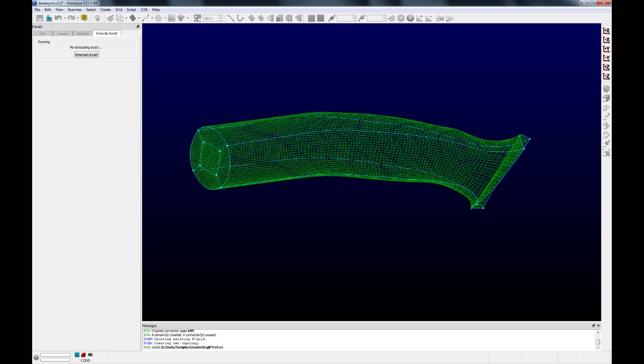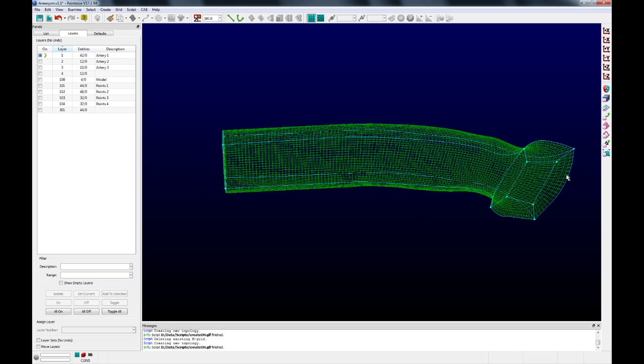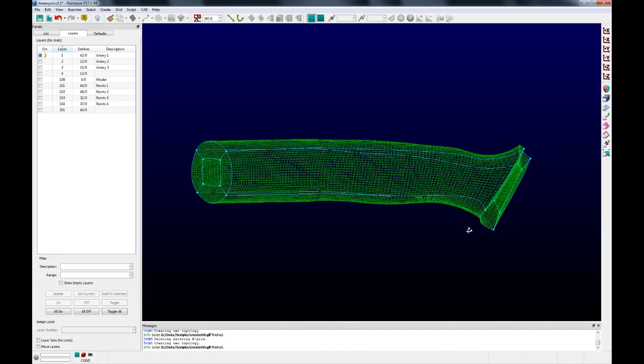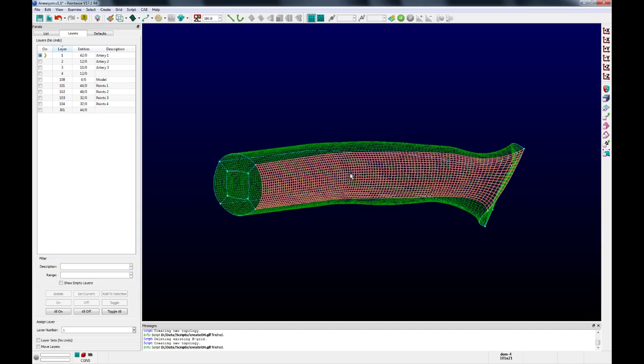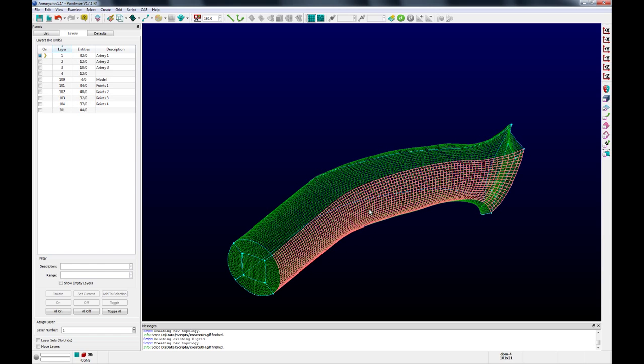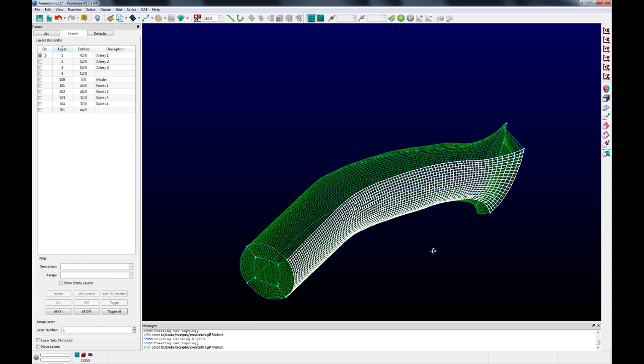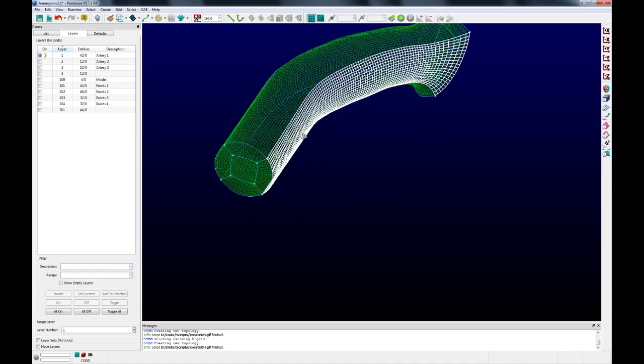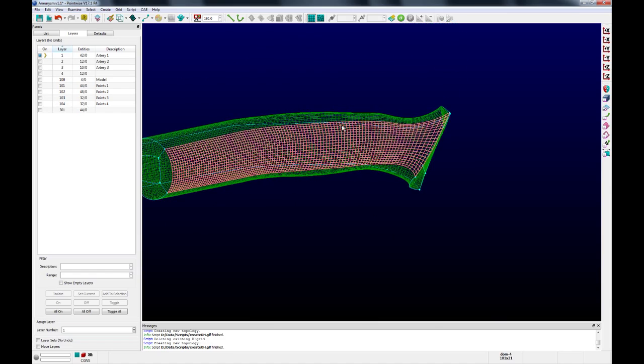Select the defaults here, but we're not going to run the solver on this end, which will become clear for reasons I'll explain in a little while. We then highlight the connectors, click Done, and we now have the OH topology there. Now we're almost there, but we found in working with this, because of the twists and turns of the aneurysm, or the artery, I apologize, it helps to divide this into two different sections. One, this nice straight artery section,